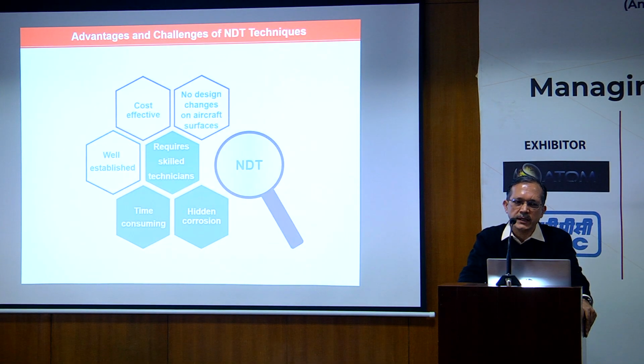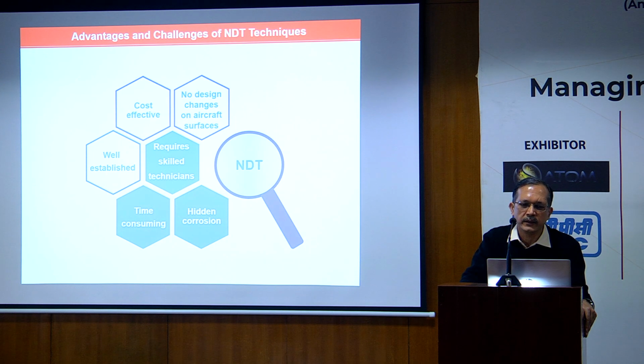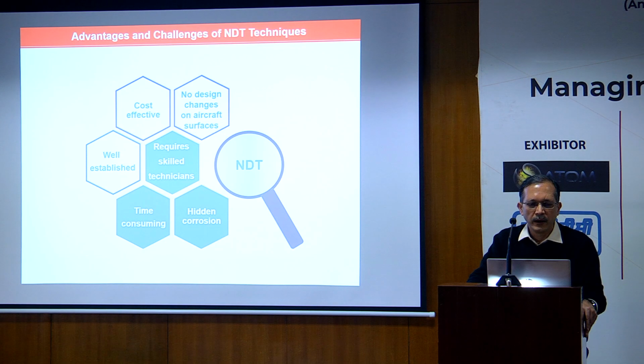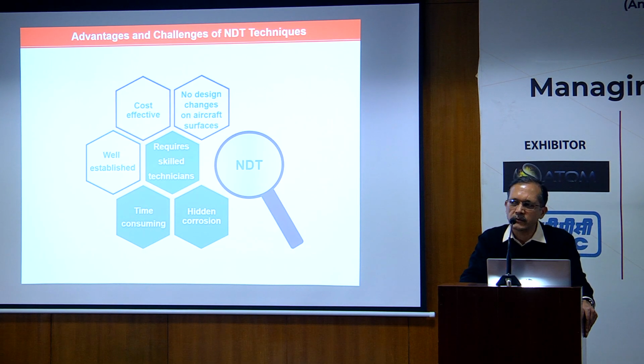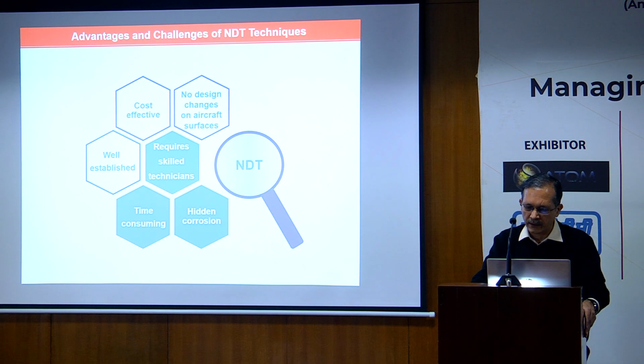Now, coming to the advantages of these NDT techniques, these are very cost effective. These are well established for more than a century, and no design changes are required in the aircraft surfaces, so it becomes very cost effective. But it requires highly skilled technicians who can interpret and analyze the data. It's time consuming, and hidden corrosion, as I mentioned in one of my slides, is not possible to detect using these techniques.